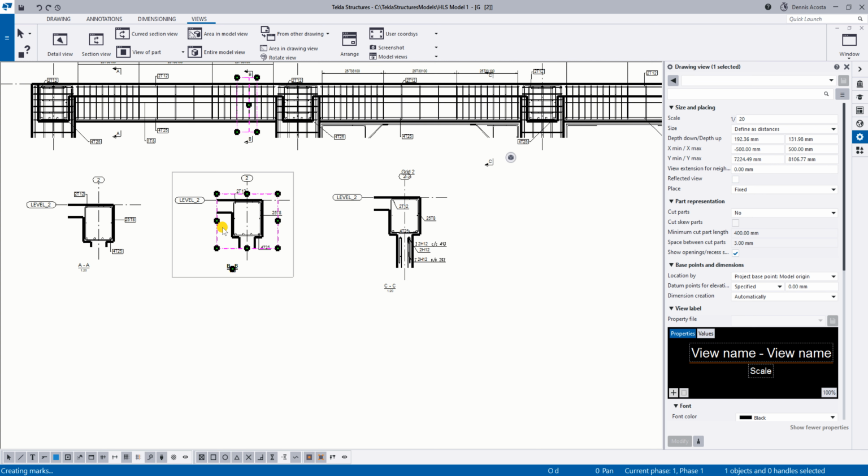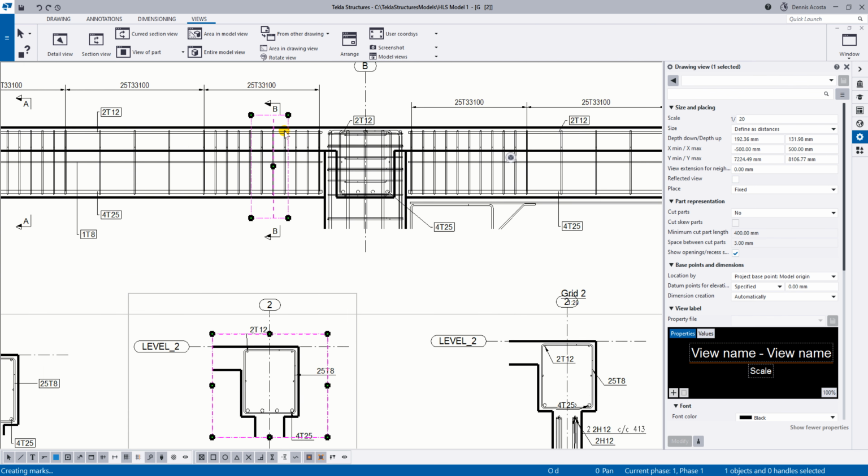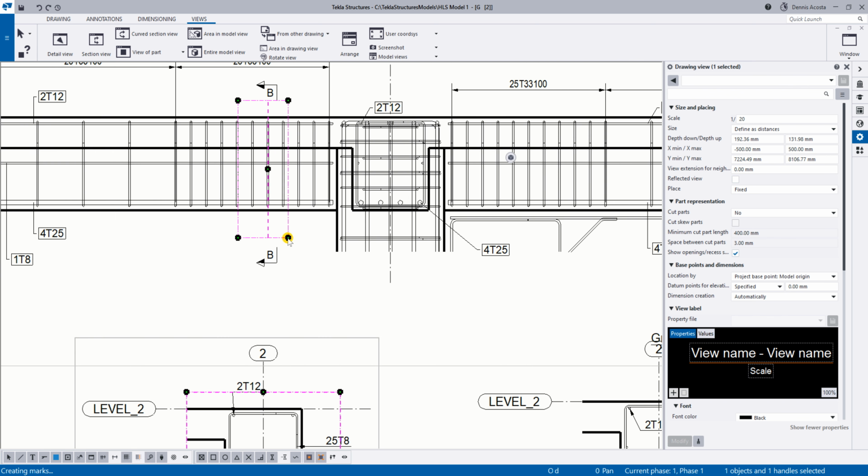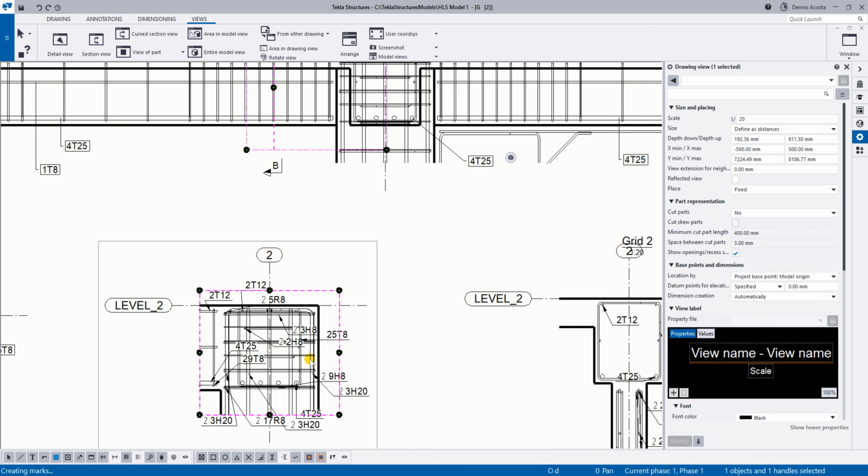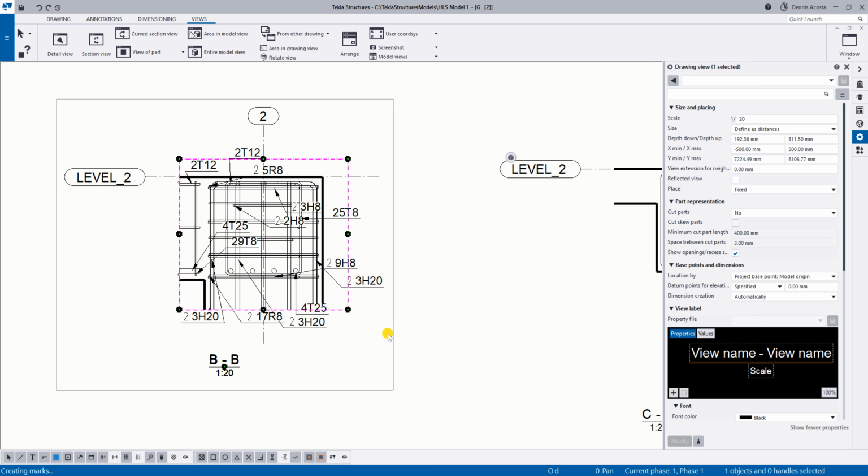You just make a section and then automatically it will get you all the proper information there. Okay? So I think it's better you make more sections. Now, how deep do I want to see the section? It depends. Here, if you notice, I have this view depth. I can extend it up to here, and then see, it will be more information.